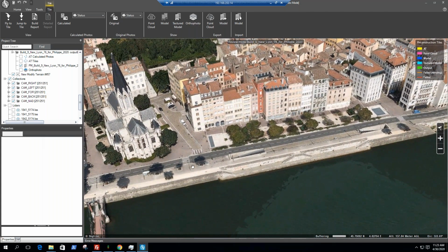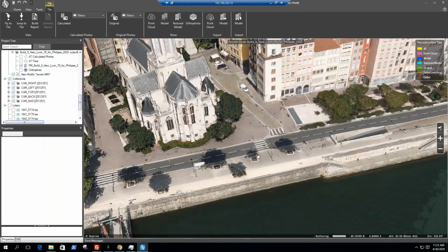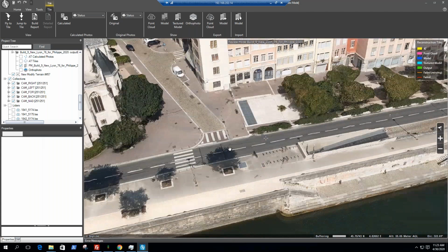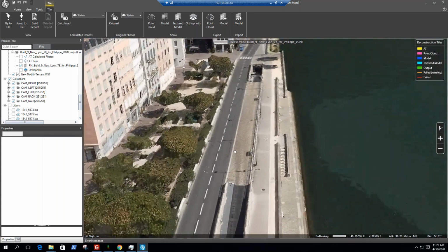One thing that could definitely be done in an external tool if classification gets used is you could remove the classes that are not necessary. Like if you classify low vegetation or cars, things that are close to the ground and might produce noise on the road, then those classes could be removed from the LiDAR files and then imported into PhotoMesh without those points.